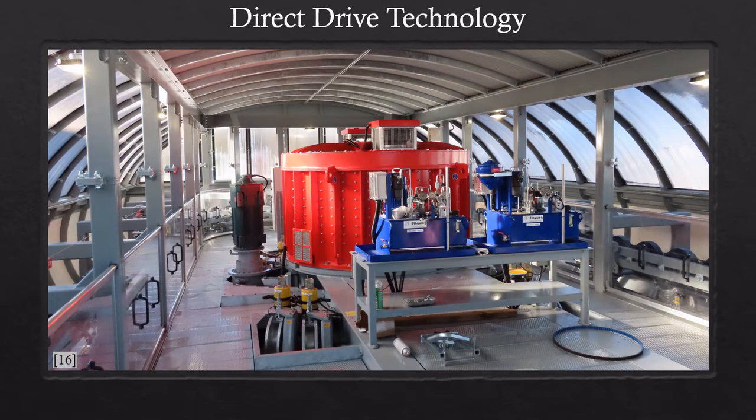The last note about drives is direct drive technology. In this setup, which is relatively new to the industry, a low-speed synchronous motor sits directly on top of the bull wheel and spins at the same speed as the bull wheel to move the lift. There are no gears because of this direct connection, so there are no friction losses or noise from a gearbox system. This setup is thus quieter and more energy efficient than traditional drive setups.